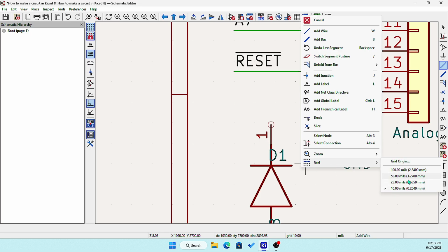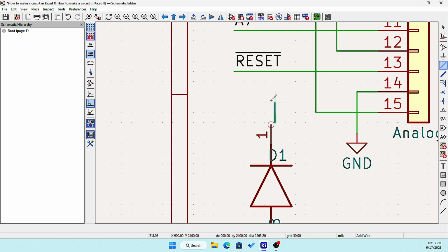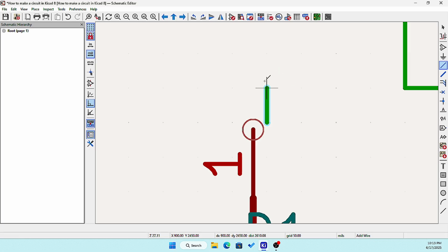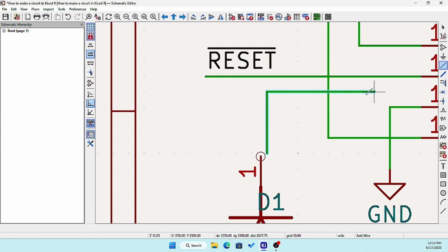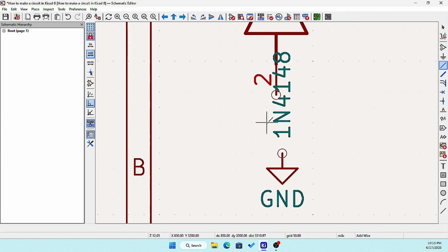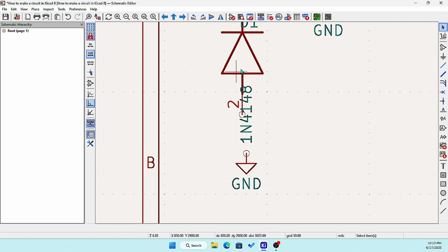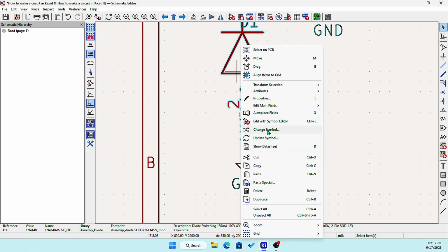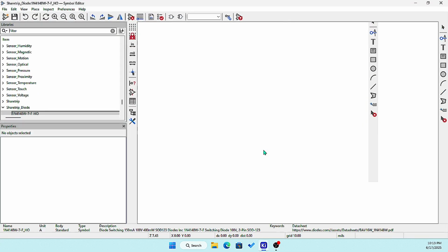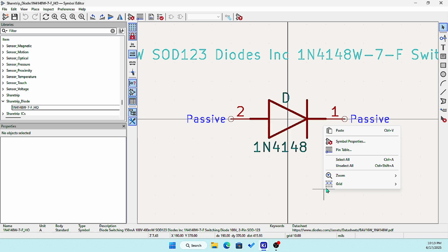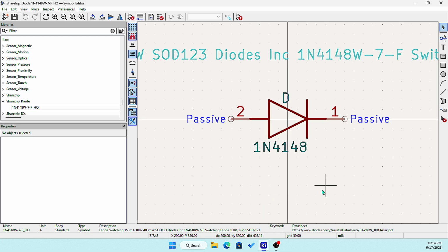All right, so let's see. I think, see, yeah, it's a grid problem. See, look, cannot even connect. Look, no, not good. All messed up. Okay, so do I go crazy about it? No. I go properties, edit symbol library. Now I'm gonna go grid 50.